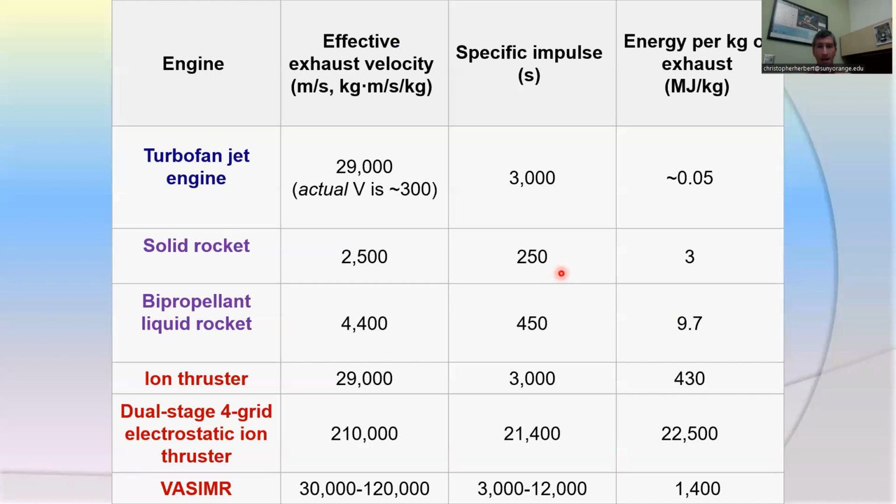So looking at rocket motors, again, the solid rocket is used for the initial boost phase because when we're going very slow, specific impulse isn't as critical. Solid rocket motors tend to be very inexpensive. You can just discard them. But in terms of efficiency, they provide very low amounts of energy for the amount of fuel that we burn.